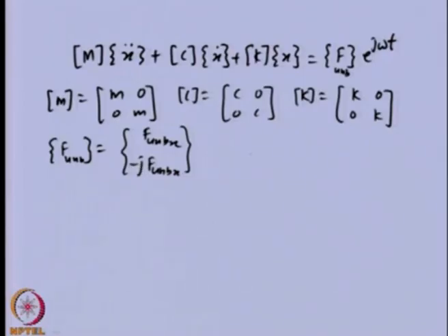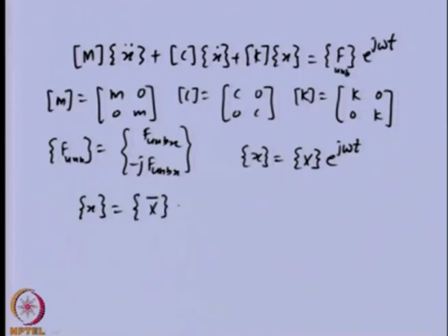Now we can assume the response as a complex amplitude and the same frequency as the force. In this particular case, the phase is taken care of inside the capital X. If we are considering, let us say, phase separately, let us say x r is the real quantity, and if we take the phase inside here, then this can be written as e to the minus j phi, this can be brought inside, and e to the j omega t.